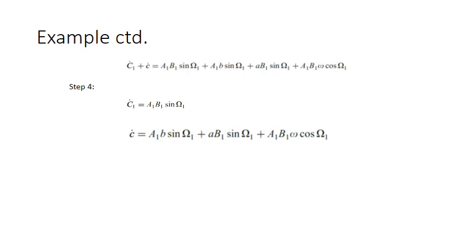So our new variables are these perturbation values, this B and this A and this omega. All other variables like A1 or omega 1 or B1, all of them are numerical values at the steady state conditions. The only new variables in our linearized equation are small a, small b, small c, and small omega. This is our linearized differential equation.